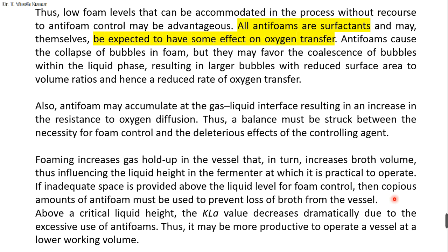So above a critical liquid height, the KLa values decrease dramatically, due to the excessive use of antifoams. So this KLa value will automatically decrease in all cases of antifoam use, but you have to adjust it. For example, if you have the mass flow controller, it will automatically increase the speed of the rotor. At the same time, that will increase the flow of oxygen also. That will manage to control the dissolved oxygen level within the vessel, in spite of adding the antifoam agents.